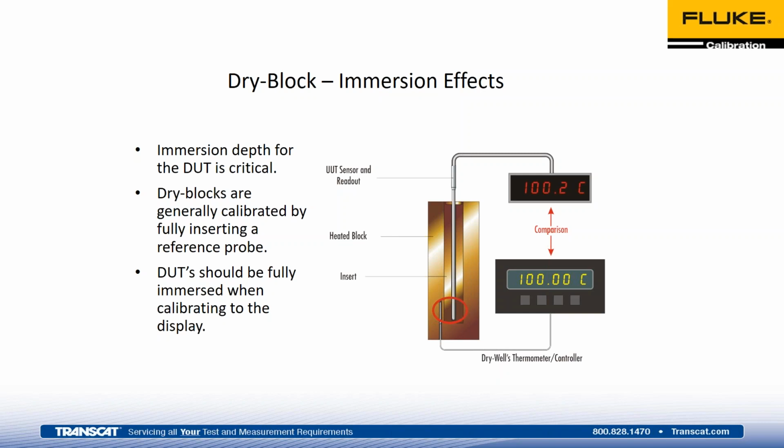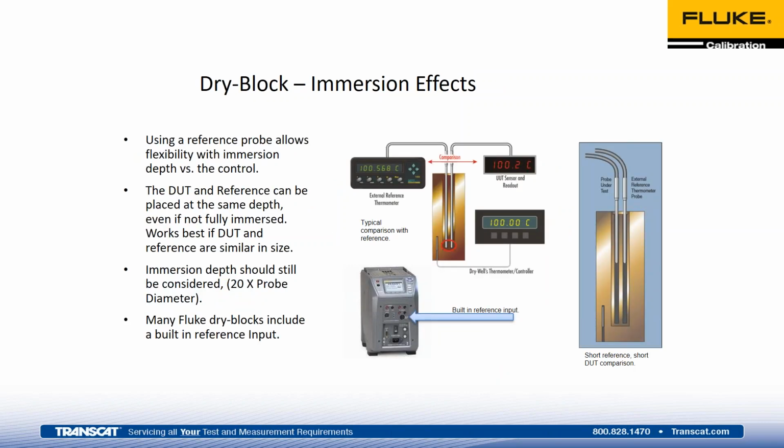So again, if you're using the display accuracy, you would want to get the device under test as close to that sensor or within that well as possible. Again, this helps reduce any errors that can be caused from being too short in the well. As we go through this, you may be from one side to the other, but we'll talk about that as we come into them.